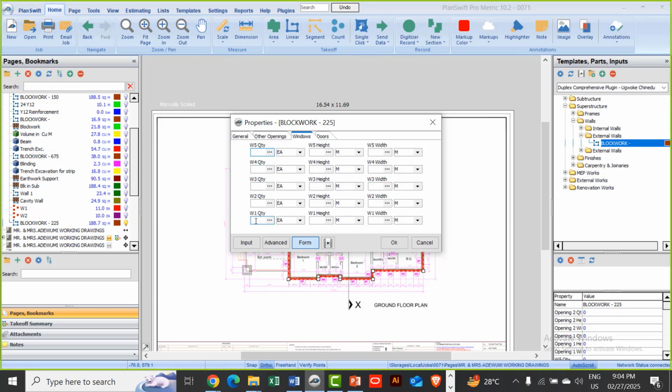We call it window 1, right? So it's window 1. What's window 1 quantity? We had 11, right? Then what was the height? The height was 1.8, if I'm correct with that. If you still remember, I have to revisit it. Okay, so what I will do is let me clean this and use window 2. Let me know if maybe there's a mistake on that formula. So we have 11. I'm assuming it's window 2. And then here we're going to have 1.8 as our height. And then we're going to have over here 1.2. So the width is 1.2 and then the height is 1.8.